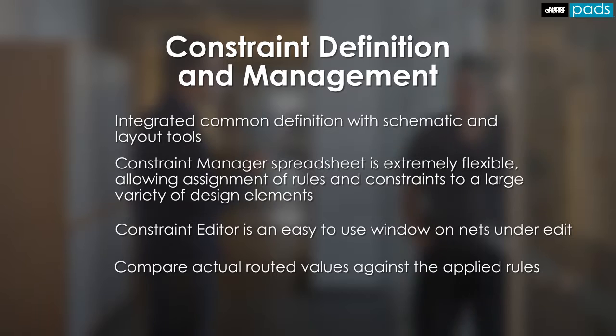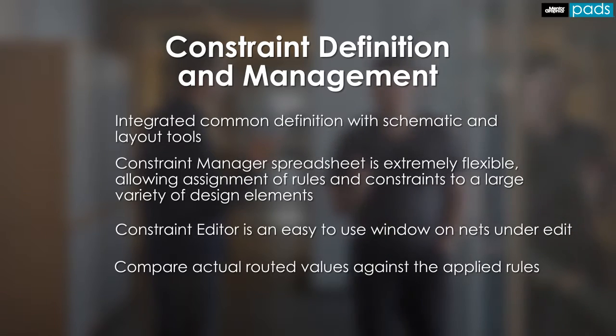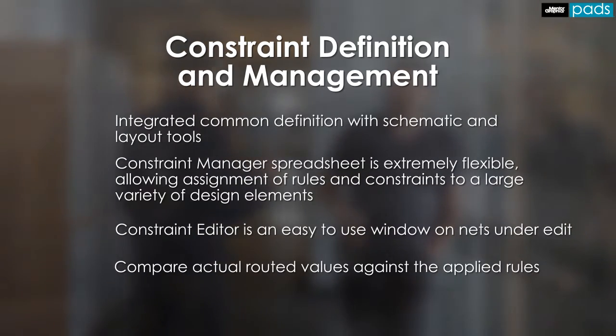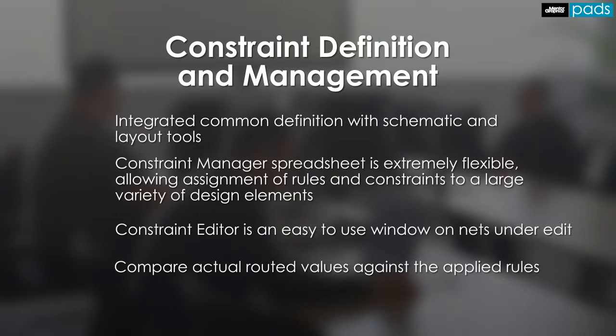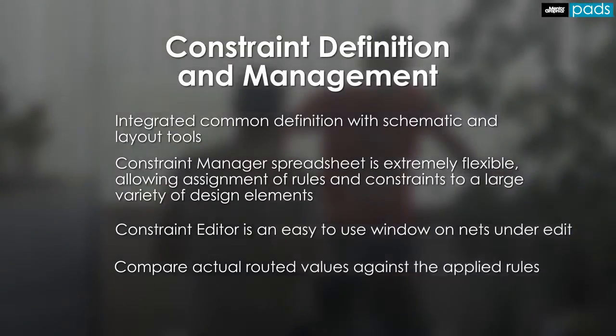Later in the design process, the actual routed trace lengths can be verified against the initial constraint definition, directly from within the constraint definition environment. So let's take a quick look at how to define and verify constraints across the design flow.